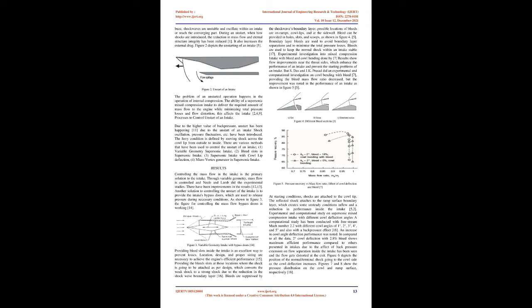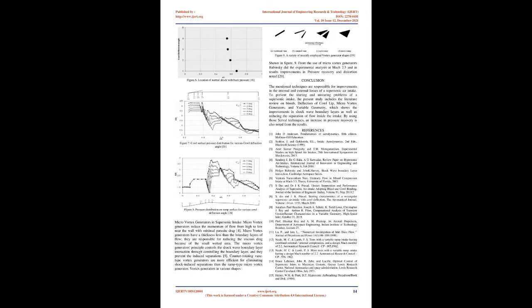It also increases the external drag. Figure 2 depicts the unstarting of an intake. The problem of an unstarted operation happens in the operation of internal compression. The ability of a supersonic mixed compression intake to deliver the required amount of mass flow to the engine while minimizing total pressure losses and flow distortion affects the intake.